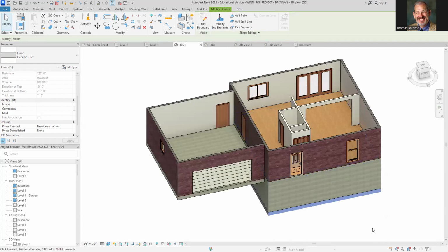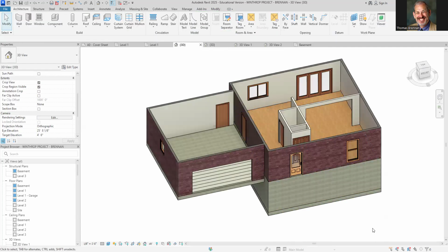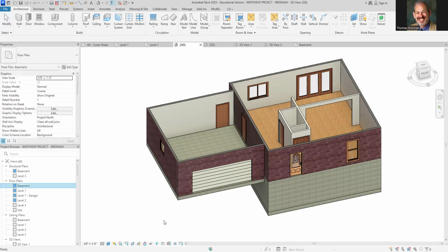I then have that, which is what we have right there. So let's go ahead and do that. I'll give you your screens back. Go ahead and do the basement walls. So you want to go to the basement level in your floor plan over here, basement. And then you're going to draw those as a 6.5 inch generic wall going outside to outside. Then you put your floor in. So I'm going to let you guys go. We'll do that.